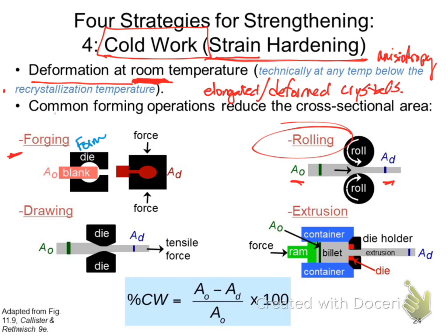If you put a piece of material, where we're calling it blank here, into the die, and the die is squeezed together, I should use red, with force, assuming that the die is much stiffer and stronger than the other material, and it won't deform as much in comparison to the blank material, you can actually just punch out the shape that you want. So sometimes we can use this for punching mechanisms, or even some sort of stamping mechanism where you don't go all the way through the material.